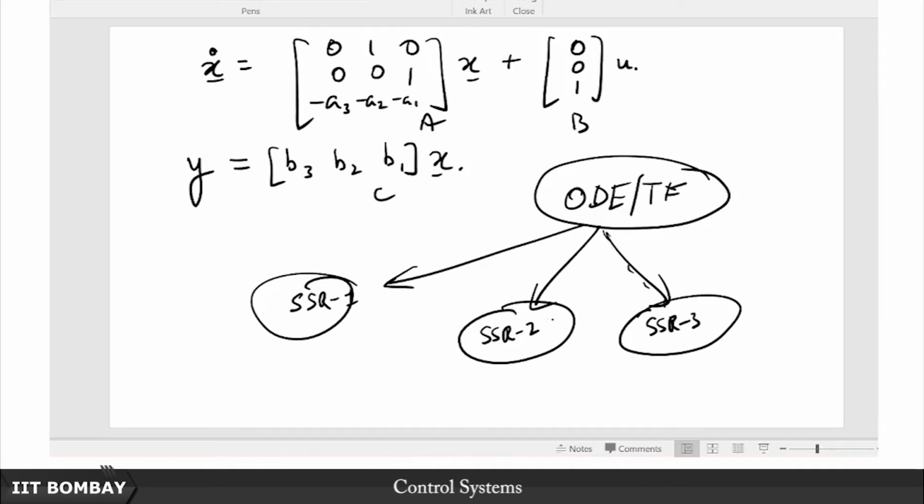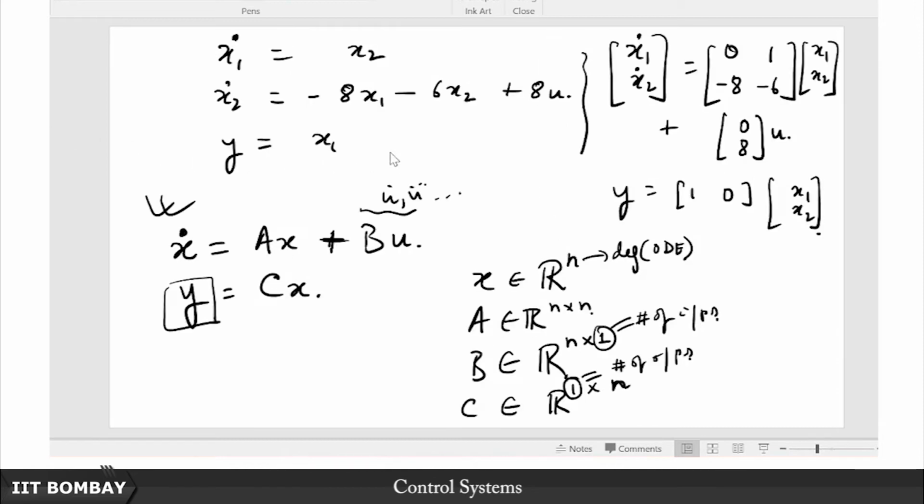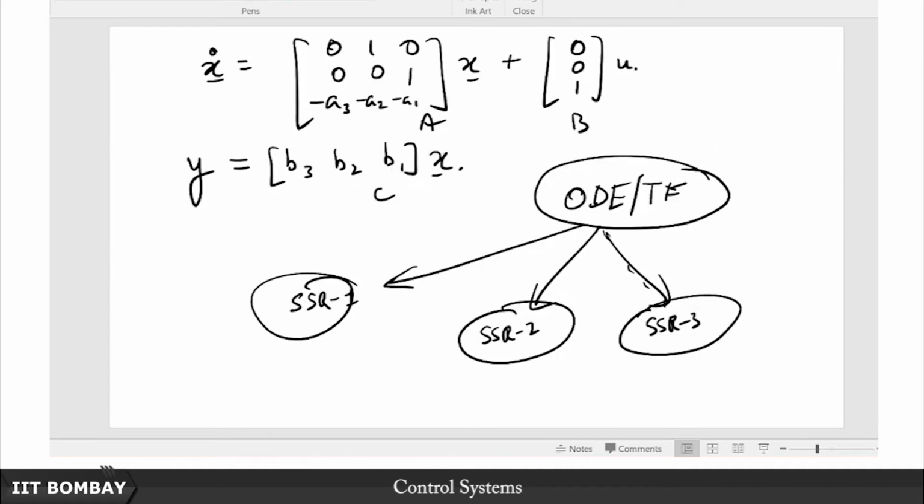So for example, one of your friends suppose is more into algebra, that person will probably prefer the phase variable method, and the other friend is more into drawing stuff and these circuit diagrams and wiring diagrams, and that friend will probably adopt the first method that I have shown. So he or she might be drawing those op amps or these integrators and calling the outputs of those integrators as the states and getting the corresponding ABC matrices, right. So of course this is not unique.